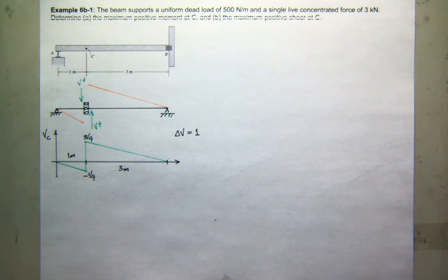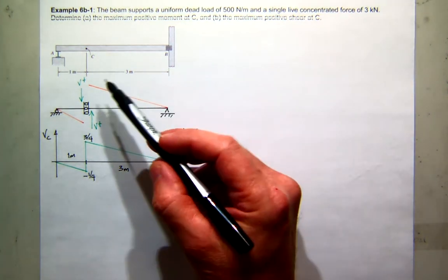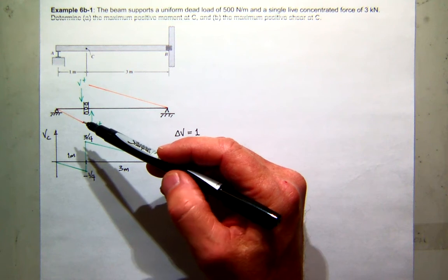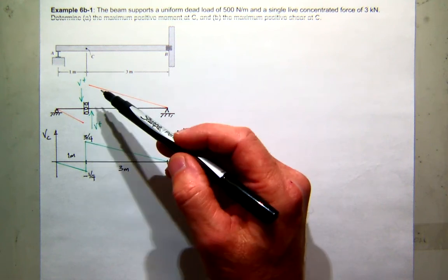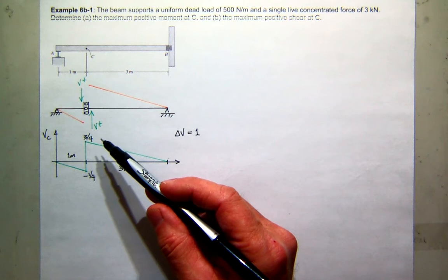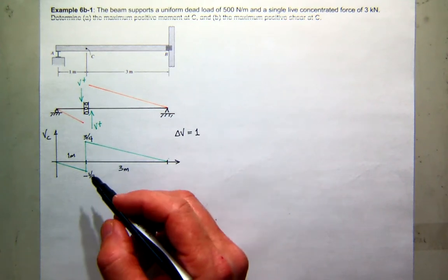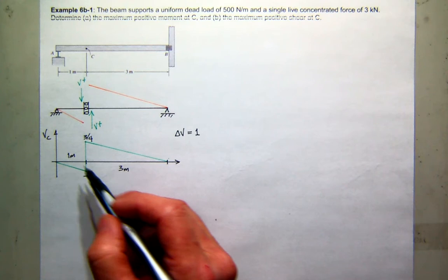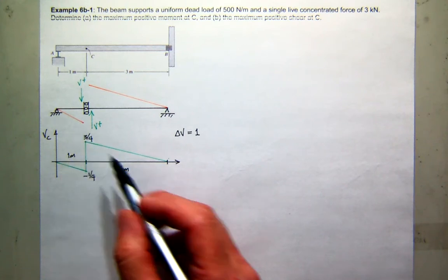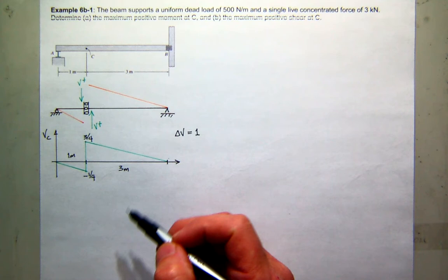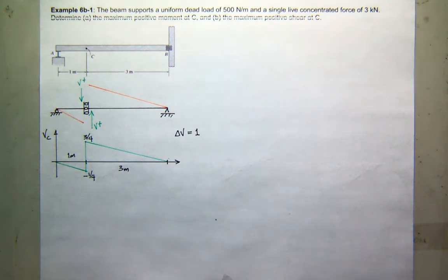Because there's really no work to record. If you wanted to, you could include this diagram to kind of show your thinking about how the Mueller-Breslau principle is working. At this point, you could write some equations if you'd like, but I think the most important thing is to always check, rise over run, 1/4 over 1, 3/4 over 3. They have to be equal. So now that I have this, what do I need to do? Just work the problem.